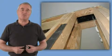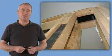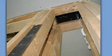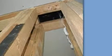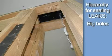One of the first things we do as we air seal is look for the big holes. In architecturally complex buildings, we see many missing fire stops, like this thick wall with an open wall cavity showing at the top. So in our hierarchy for sealing leaks, we always want to seal big holes first before little holes.